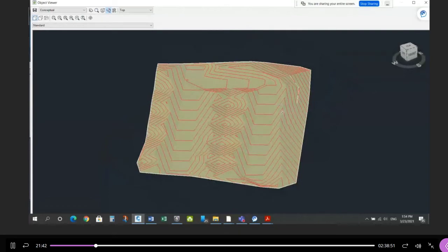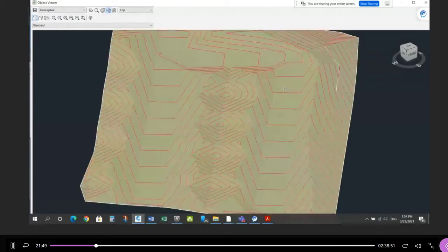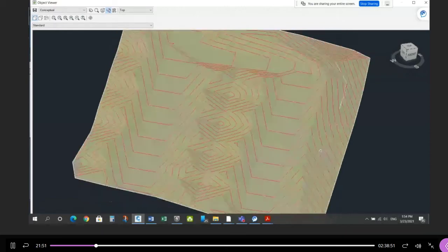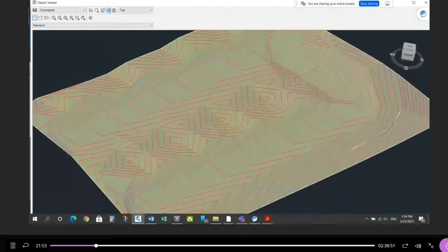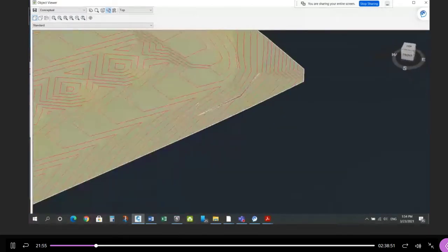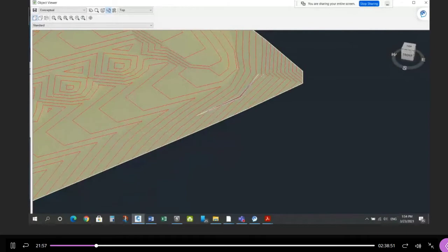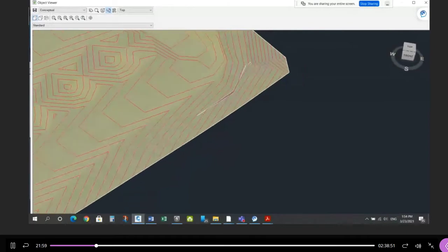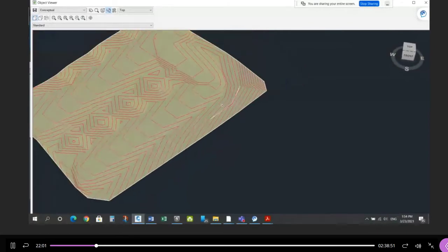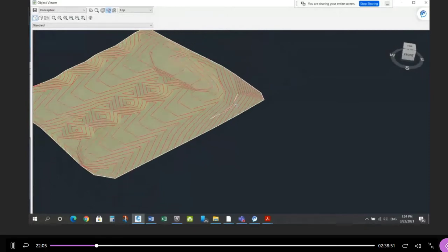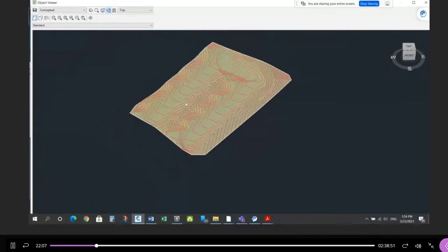These are the split points, right? So water drains this way and water drains toward the road this way. So that's your split point all lined up through here, okay, on these lots here. And then if you did the details, you would have had a little bit of back splitting here. So you would have seen a little bit of a 3-to-1 slope across here somewhere, okay? It was a little steeper than 3.5 or 4% in here, so there was a little bit of back split to do here. So that's what the surface looks like.